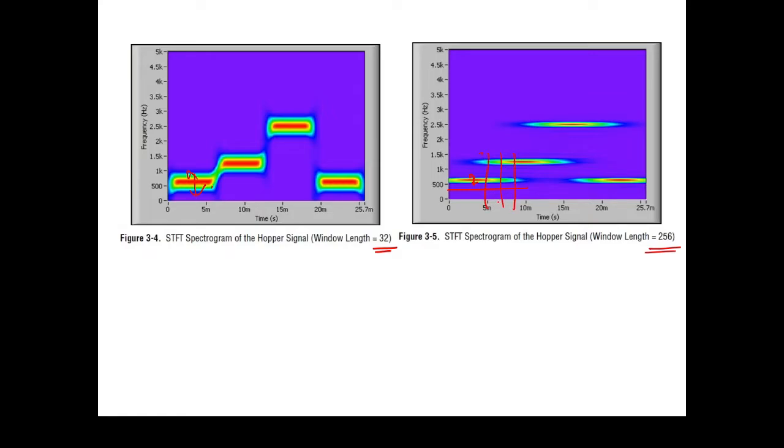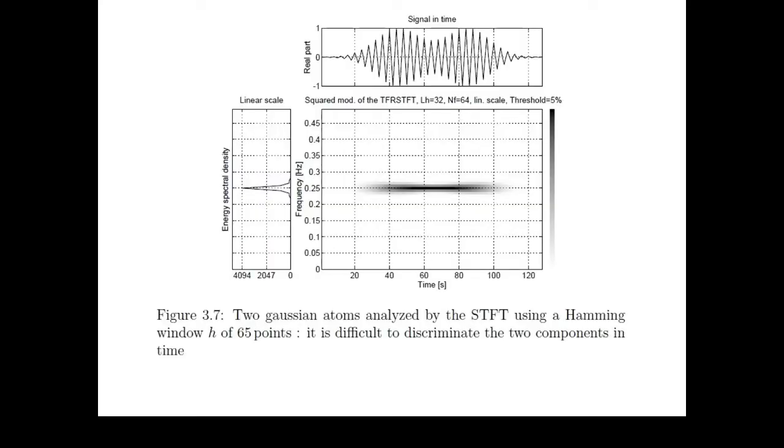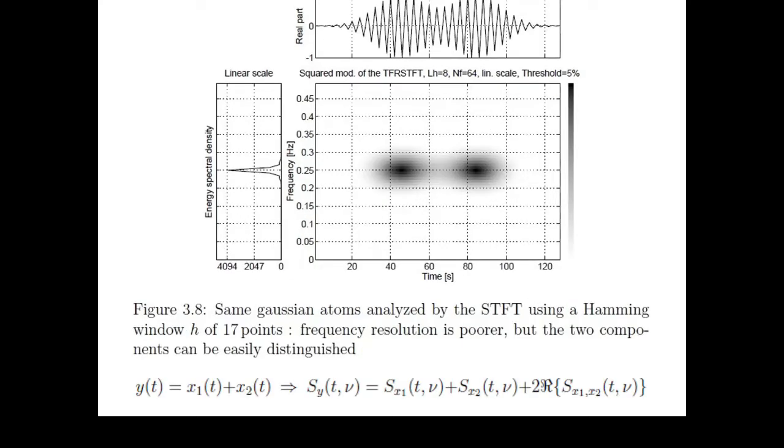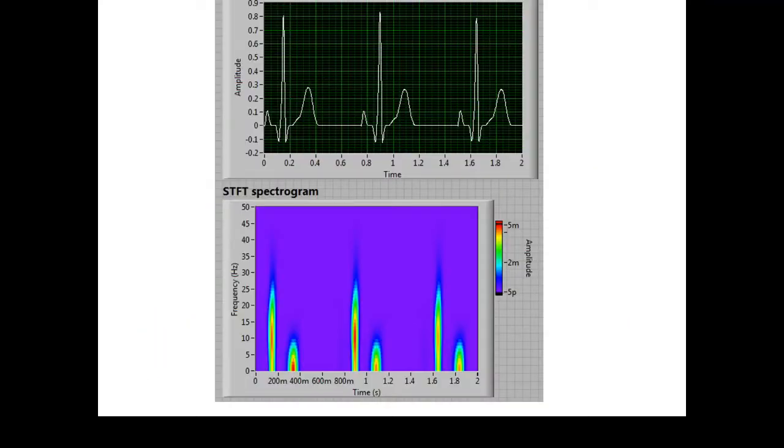So this is what your time spreading and frequency spreading can do with your analysis, and hence choosing the window size is of utmost importance for the STFT transform.